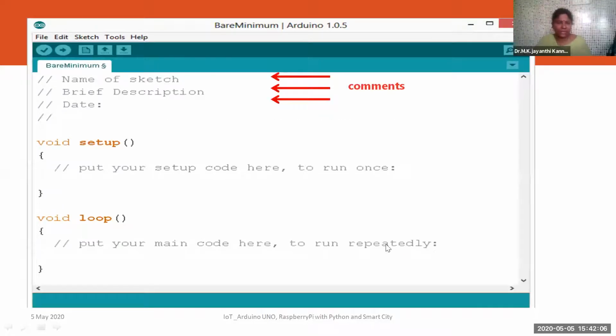And this diagram shows you a small program written in Arduino 1.0.5, the bare minimum. Here they are using some comment lines. They are putting slashes, and the name of the sketch, brief description, date of the program, author name, all those things can be written within the comments. These are the comment lines, followed by the void setup function, which will be executed only once, and the void loop function, which will be repeated a number of times until the condition is satisfied.